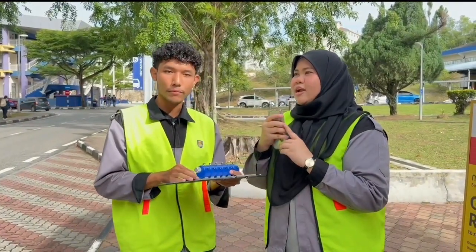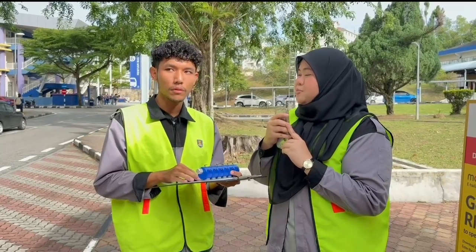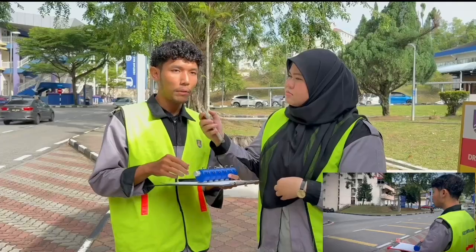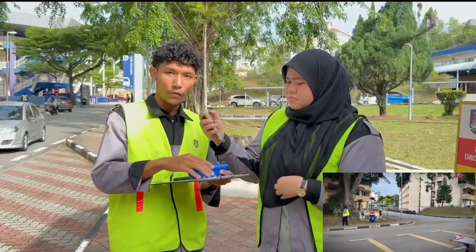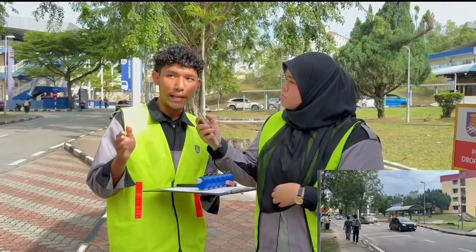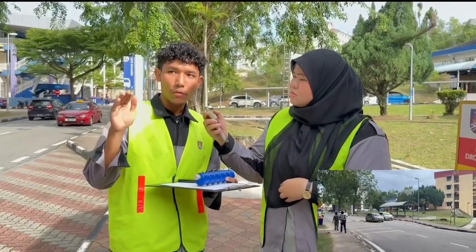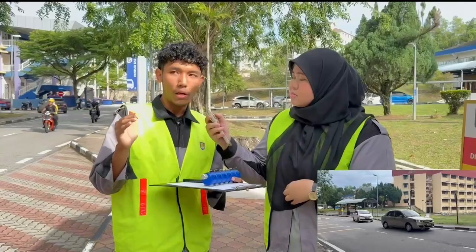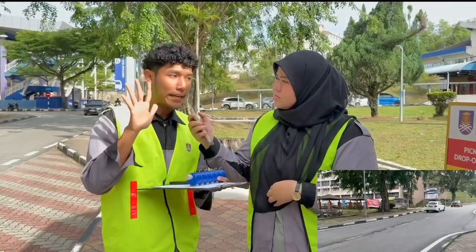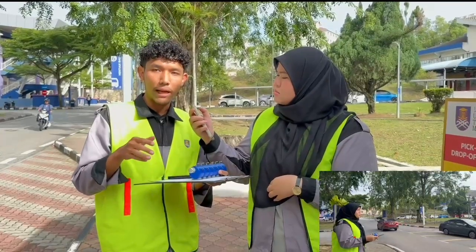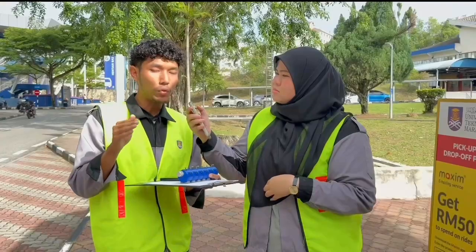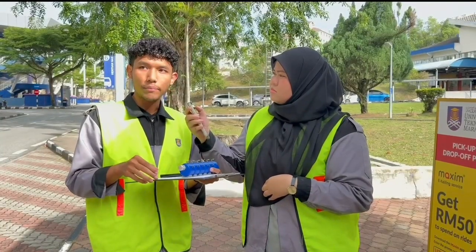Can I ask what a traffic volume study is and how the procedure is carried out? Today we chose a straight road for our survey. Before that, what we need is a multi-tally counter, a field data survey form and a stopwatch. The procedure is quite straightforward. First we select a clear observation view with clear traffic flow, and we must conduct it during the peak hour. Today we decided to conduct it for 1 hour with 5-minute intervals. We measure the number and type of vehicles passing through this straight road using the multi-tally counter according to the categories, and that's all.